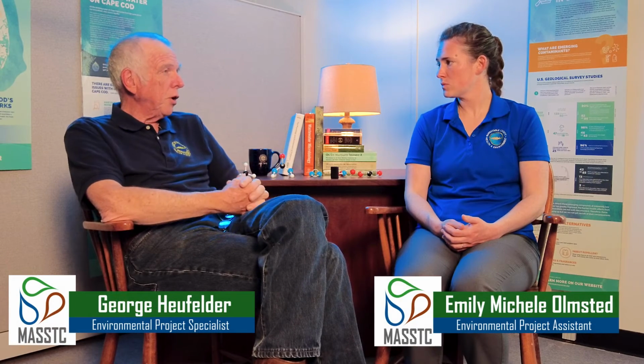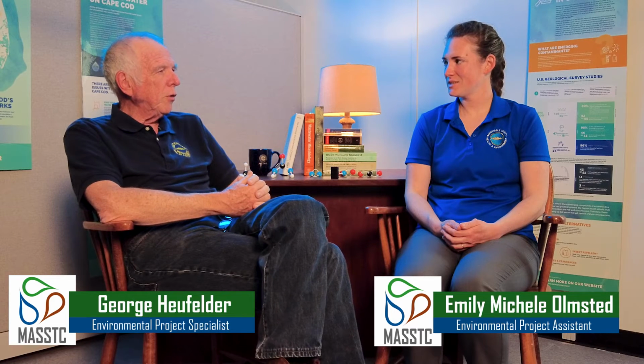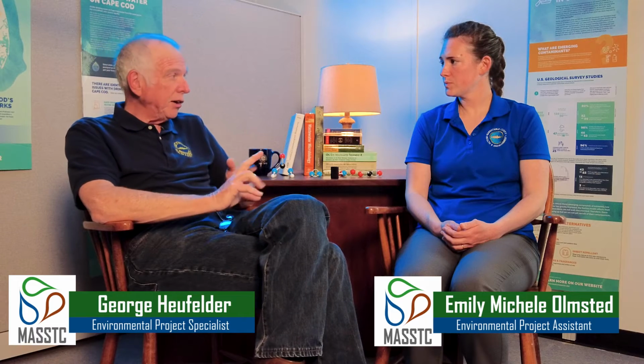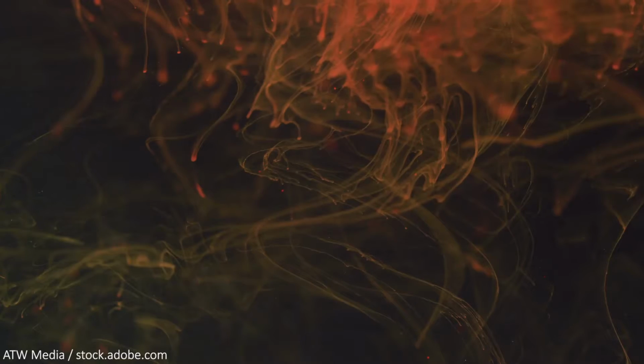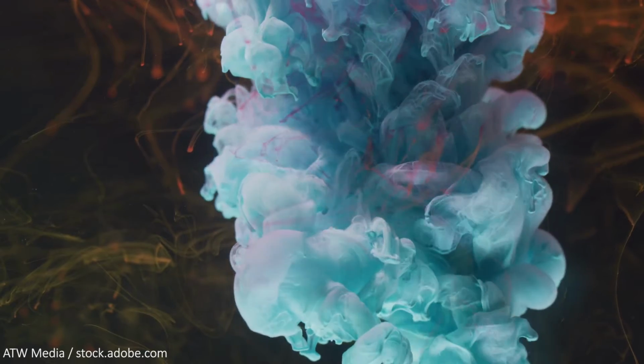So samples will tell you quite a bit about how your system is performing. Yeah, well, samples is really the whole picture. I mean, there are some visual cues. If you go there and the thing's turned off and there's nothing working, then you've probably got a pretty good clue that the system isn't going to remove what it's supposed to remove. But given all the visual cues, nobody's unplugged it, you see everything working, you look down there and you see the bubbling, and the unit looks like it's on a showroom floor, then you'll say, okay, now I really need to look at the chemistry and the biology of what's happening in the system.